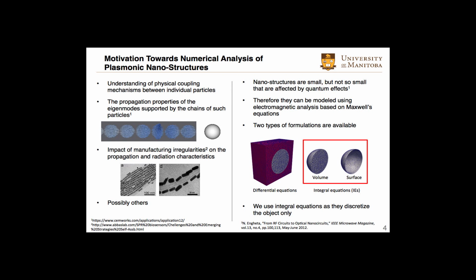Two types of formulations are available. One is differential equation and the other one is integral equation. Differential equations are good in the sense that they are simple to implement and they can be effective. But the problem with them is that you have to discretize the entire domain. But rather in the integral equations, you will just have to discretize the volume or surface of the object. So in this study, we use integral equations.